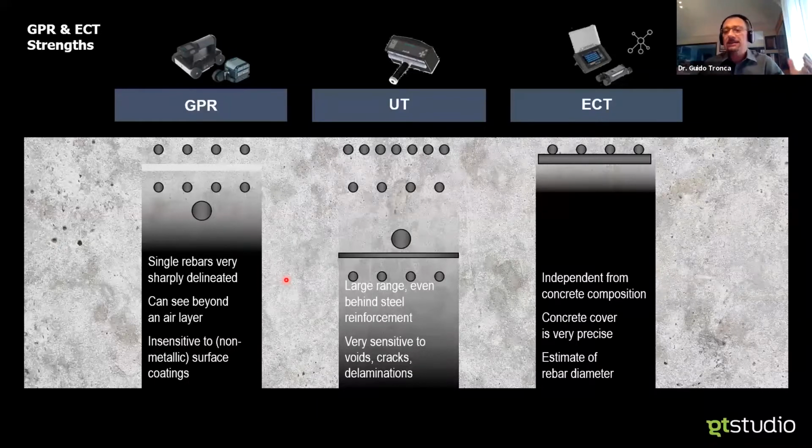And as state of the art today, it is the only approach that I can have for having the estimate of a rebar size under lucky circumstances, not under all scenarios, but if there's one guy that can guess a rebar size, it's an eddy current based rebar locator.